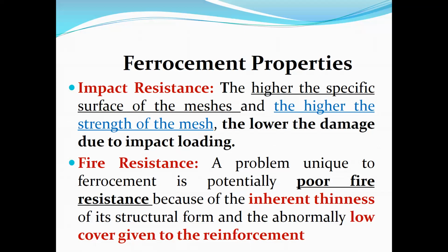A disadvantage of ferrocement structures is fire resistance. Between steel structure and concrete structure, concrete is better in terms of fire resistance. A concrete wall or a brick wall will give fire resistance for a long time. But a ferrocement structure, which is only 1 to 2 inches thick, has poor fire resistance, because of the structure, and there is no concrete cover in it. So in fire resistance, this is a major disadvantage.